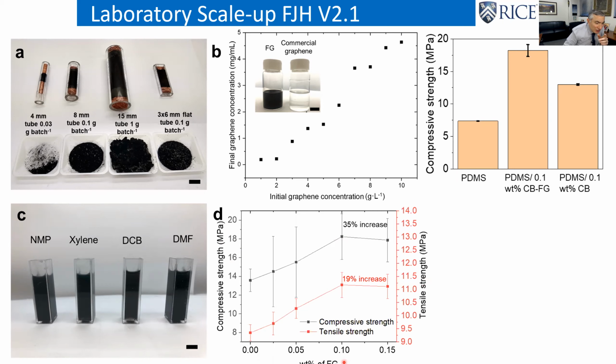The reason that's a big deal is because 8 to 9% of all CO2 emissions in the world come from the making of concrete. You take metal carbonates, you heat them up to 2100 centigrade. They form metal oxides, and you're blowing out CO2. Then you have to heat that furnace to over 2000 C, so you're blowing out CO2 on that. Then you put that concrete in a truck, you add water, a lot of water, it's very heavy, and you ship that off to a site. 8 to 9% of all human CO2 is from the making of concrete. If you could use 1/3 less concrete, that's a big deal.